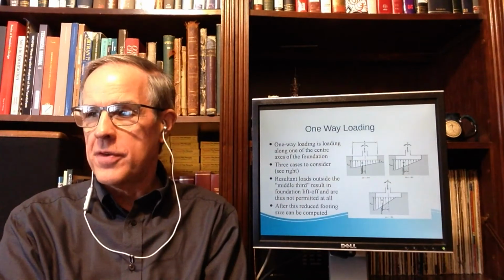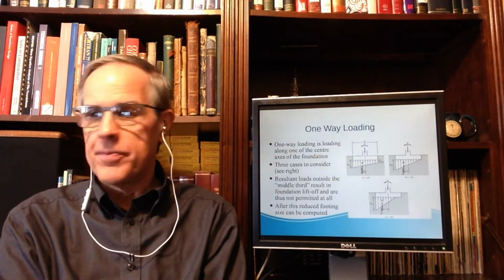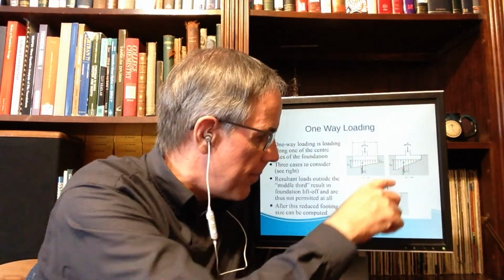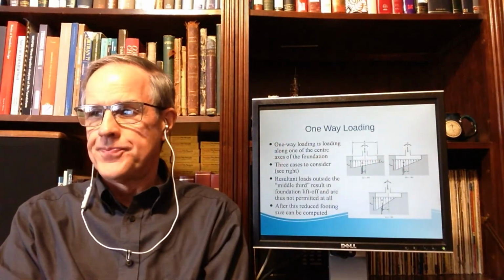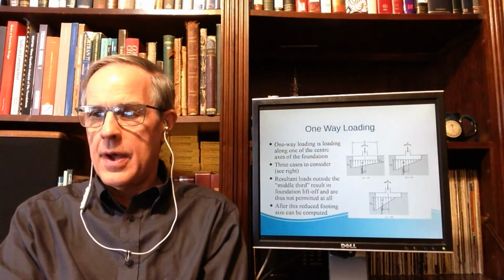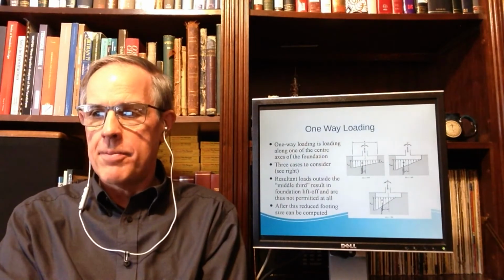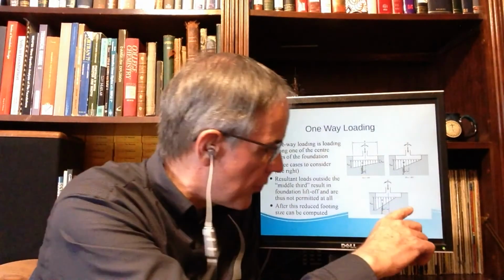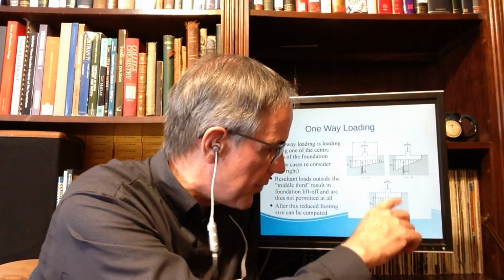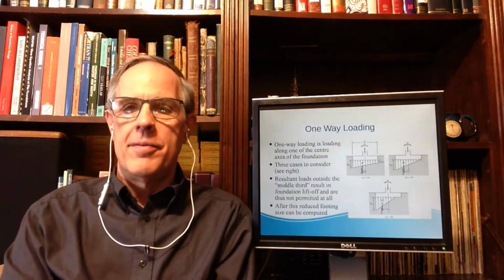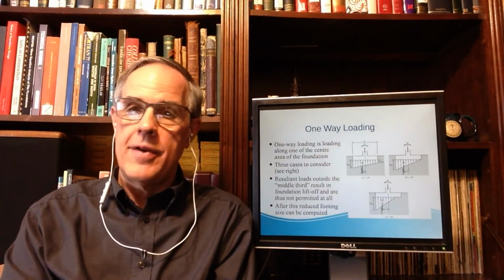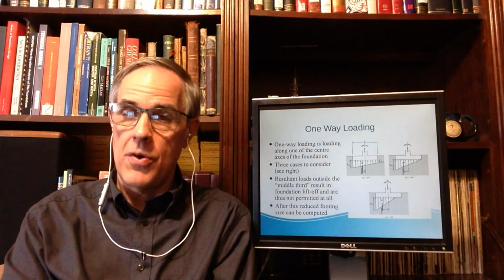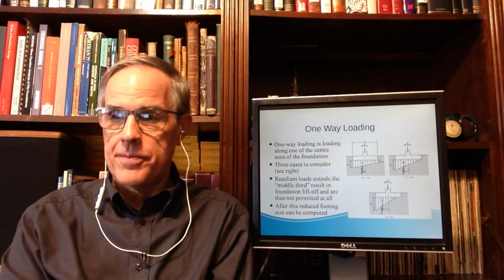If you get to a certain point, actually here, then one end of the load is 0 and the other one is the maximum. Once you get past that point, you get a situation where you have essentially what should be a negative load, but face it, people, we don't have tensile loads in foundation interfaces like that. So those are not permissible.